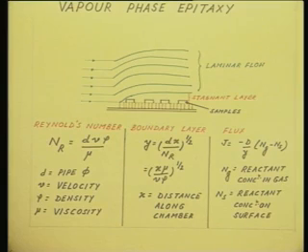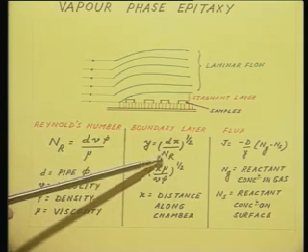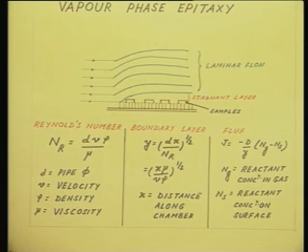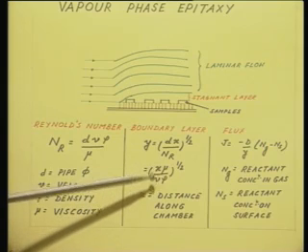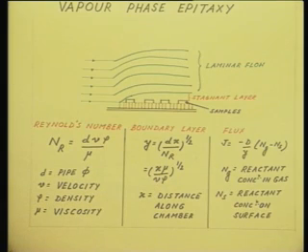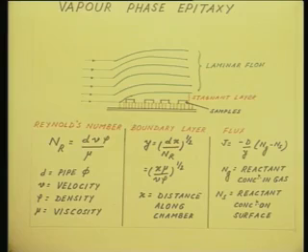Okay. Now, the width of the boundary layer or the stagnant layer is related to the Reynolds number by this formula. Y, that is the width of the stagnant layer, is given by d times x divided by Nr whole to the power half, which by substituting the value of Nr from the first equation, we can write as x times mu divided by v times rho to the power half, where x is the distance along the chamber. So, you can straightaway see that the width of the stagnant layer is going to increase as we move along the pipe, which I think should be obvious from the figure also here.